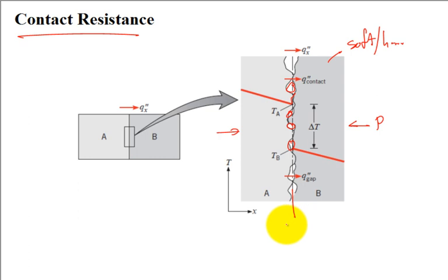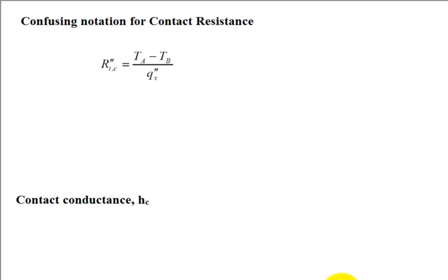Anybody work with electronics? You have that little thermal grease. Sometimes they call it silver oxides or whatever. And then you just put a thin layer before you put your heat sink on the CPU. And then they clamp it down, little springs, click, click. Well, they have all kinds of high conductivity names for those, but they're usually better than air, but they're really not great. I mean, it's better if you could get a great contact. But this is a real problem.